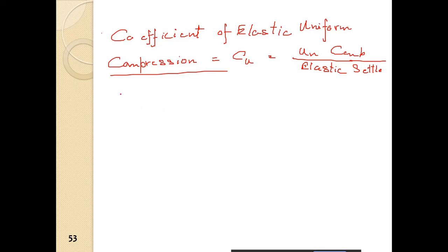Then we have the coefficient of uniform elastic shear, and we can relate that to the spring constant. So Kz is equal to Cu into the area of the foundation. So that is Kz.